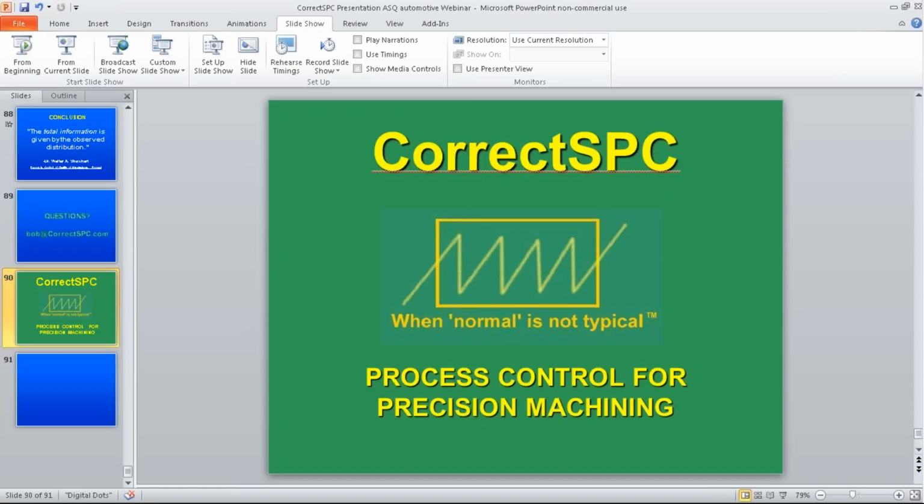Have another comment. Bear with me. Makes a lot of sense. Also, with exceptionally long wear or trending, such as a laser cut, for example, where the strength of the laser degrades, I'm assuming then that a traditional Shewhart with appropriate sample size, if not normal but random, would be an appropriate approach. The high-low makes much more sense for those distributions which have definite trends for sure. Thank you. Yeah, absolutely.